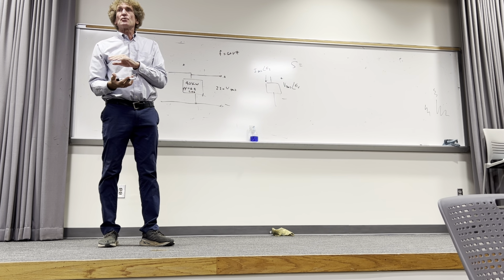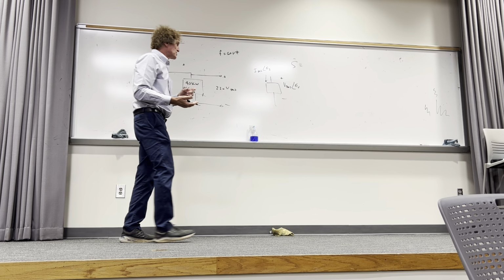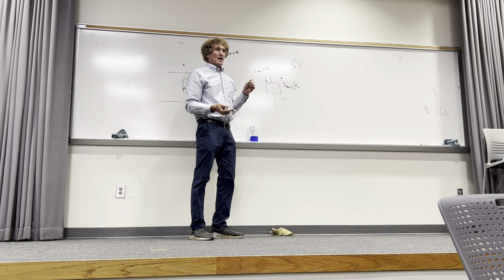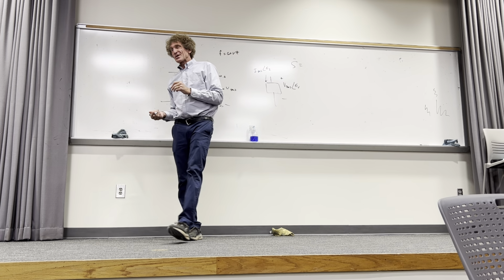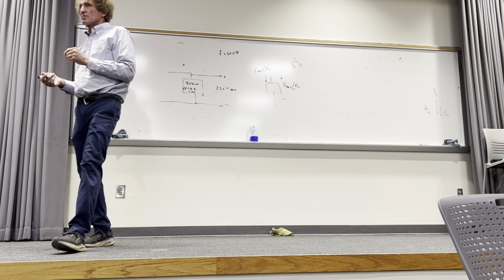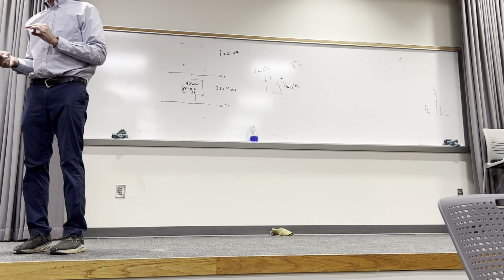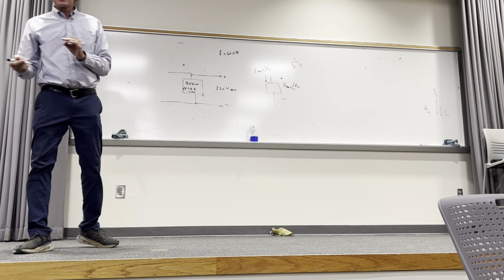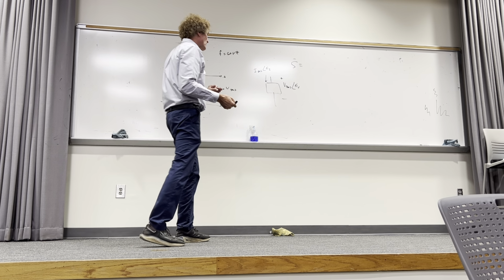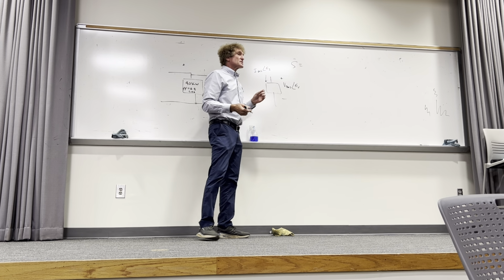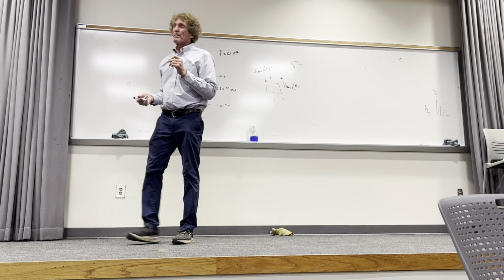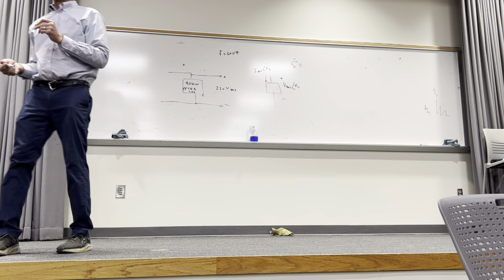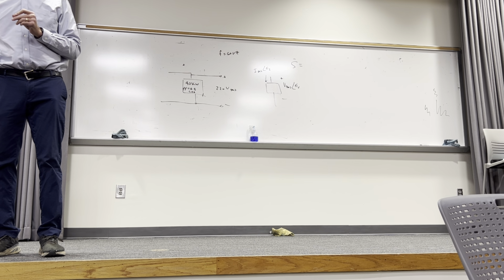Now, if it is a pure resistive load, if this is just a resistor here, then the voltage and current are what's called in phase. The angular difference will be 0. Y'all follow me? If one was at 45 degrees, the other will be at 45 degrees. If one was at 0 degrees, the other will be 0 degrees. If this was a capacitor, if the voltage is at 0 degrees, the capacitor's current would be at plus 90 degrees.